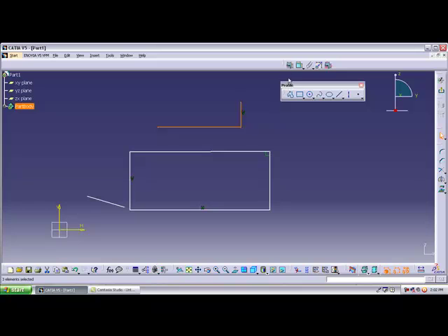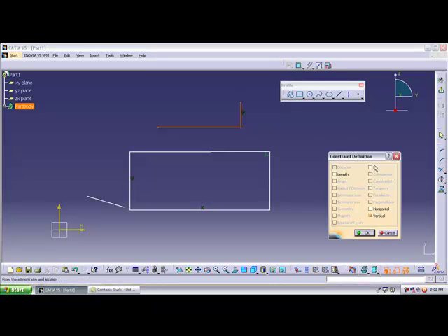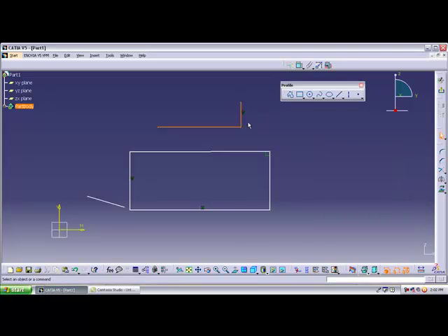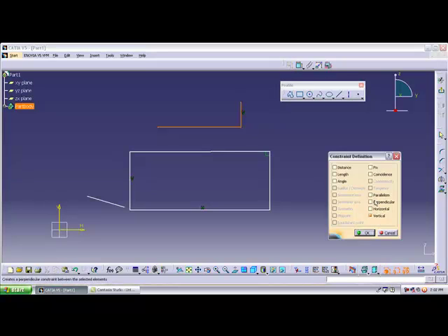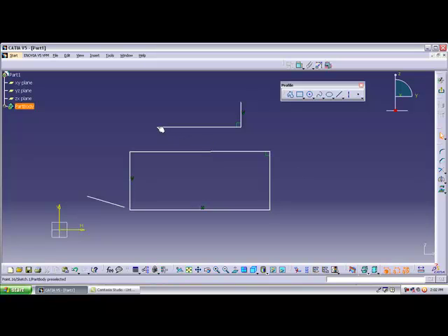One more time, I want to make the perpendicularity between these two things. Select the two objects and select the constraints. So I want to add a relation. Sorry, one more time. Select these two lines and select the joint constraint. You will get perpendicular. Okay. See, right now I added the relation. By adding horizontal and vertical, you get the perpendicular. By making one vertical and perpendicular, it will automatically get horizontal. Okay, like this we can add different types of relations.